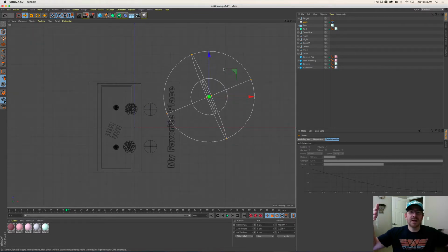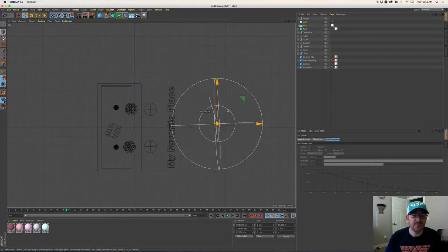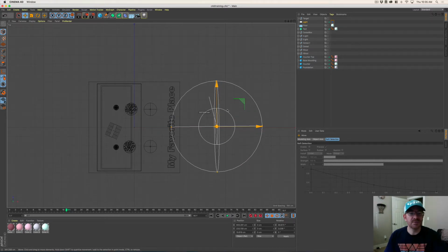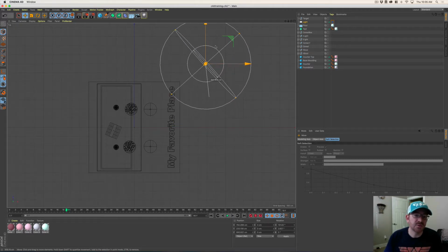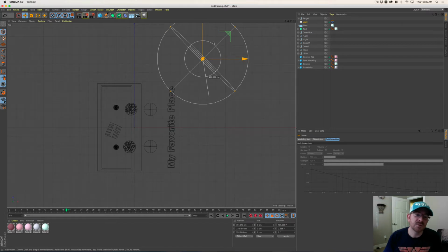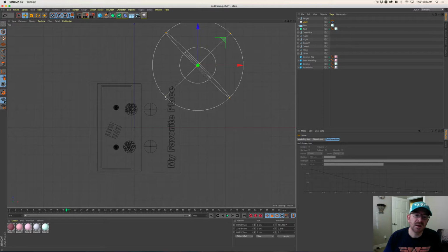What I want to do is, my fill and my key light need to be at 45-degree angles. So if I think about this as the front view, if my light's pointed at my scene from the front, I need to drag my light to a 45-degree angle. So it's kind of like hitting the corner right here. All right. Then I also probably need this fall off to come in light probably towards my cereal bowl.